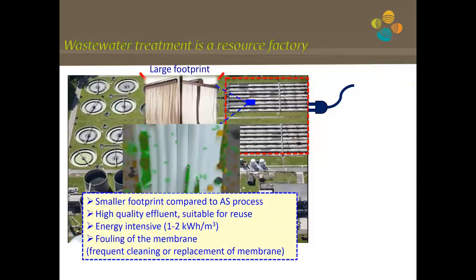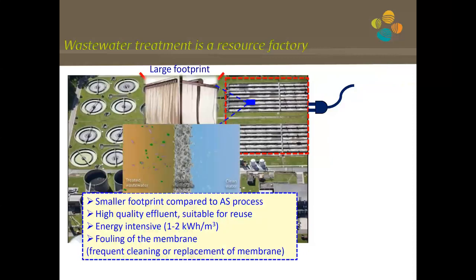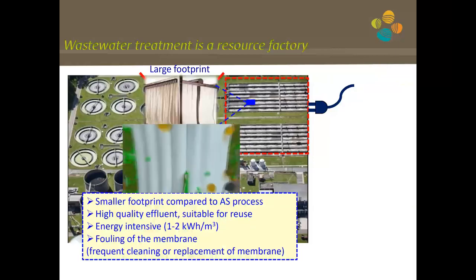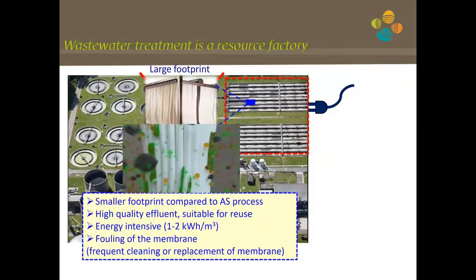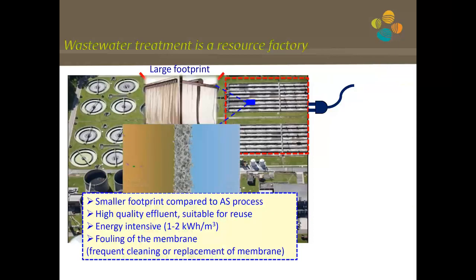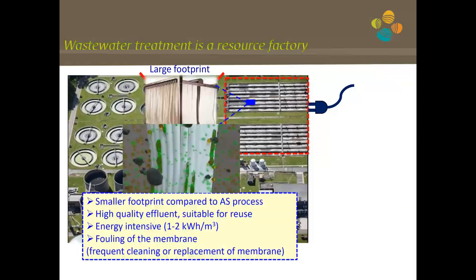However, there is a growing awareness that the current paradigms of wastewater treatment are no longer adequate to meet the demands of a rapidly growing human population and urbanization. Thus, environmental engineers slightly modified the existing activated sludge process by integrating it with porous membranes, and we call this aerobic membrane bioreactor technology. This is the current state of technology for wastewater treatment and reuse.